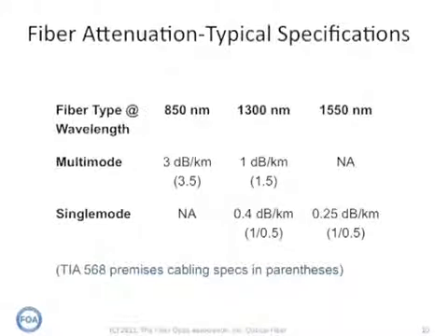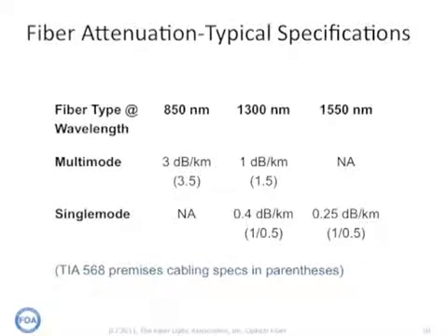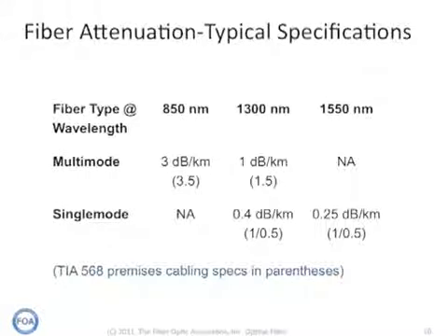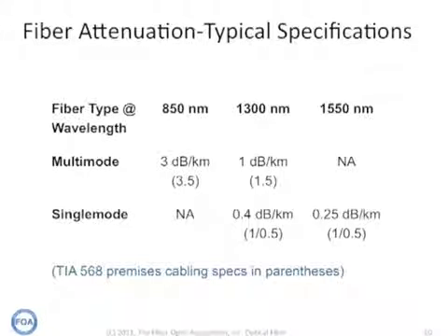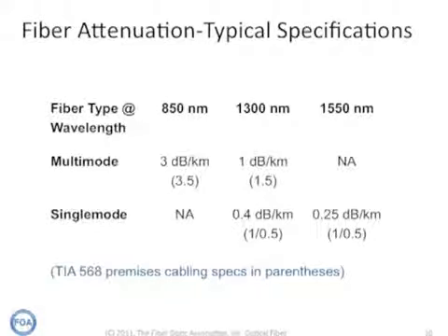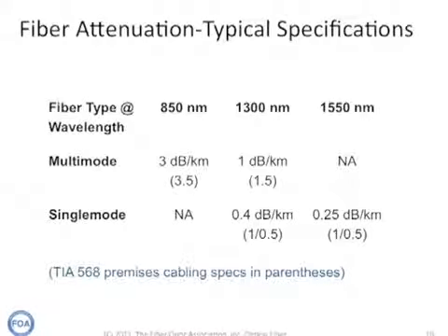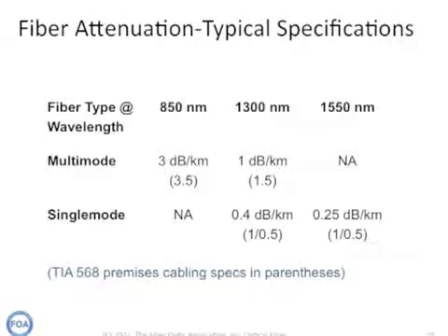You can see the same specification changes occur with single mode fiber. And oh, by the way, these are typical specs. The actual standards sometimes have much higher losses just to make sure that all fibers can meet the minimum specifications. Those are not typical specs.